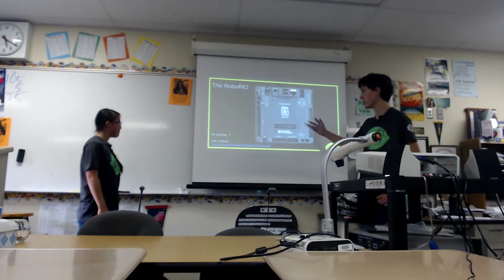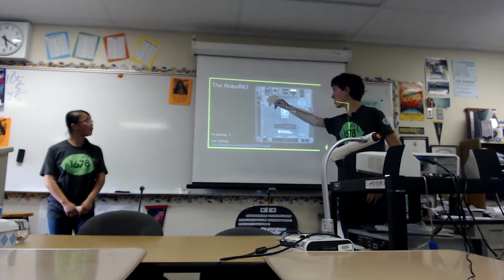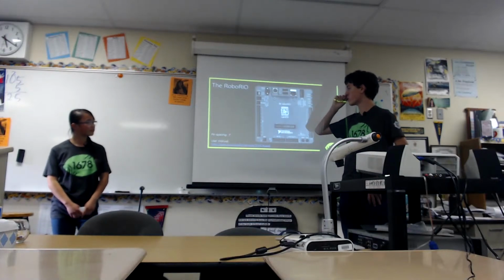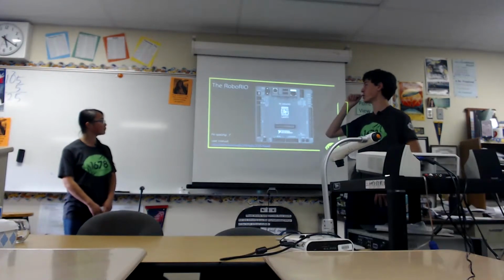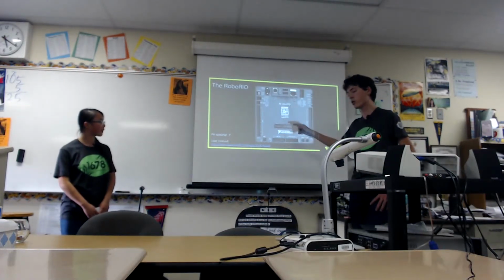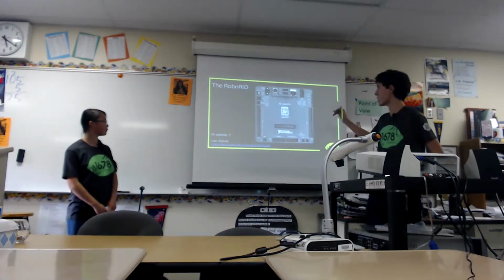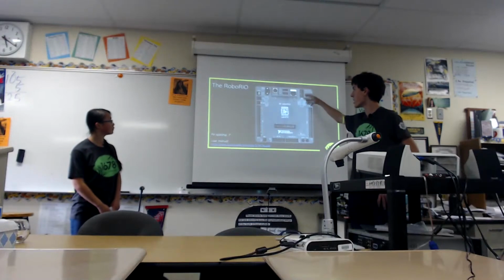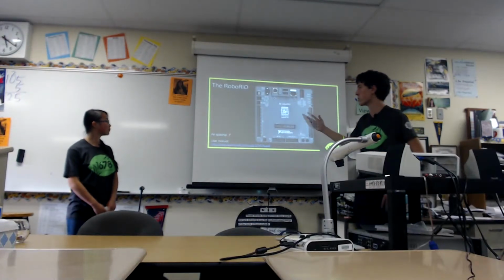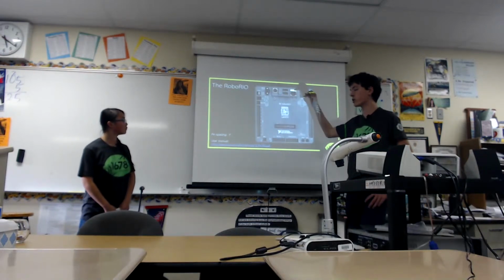So here you can see the RoboRIO. We go through the ports. You've got the CAN port up there, I2C. We'll talk about that later. RS232, I don't think we talk about that in this presentation. Then you've got digital input/output ports, your RSL relays, analog inputs, and you've got PWM, SPI here, Ethernet, 2 USBs for stuff you want to use in your robot, like USB cameras, and then USB-A for connecting to computers, and then you've got your power input.